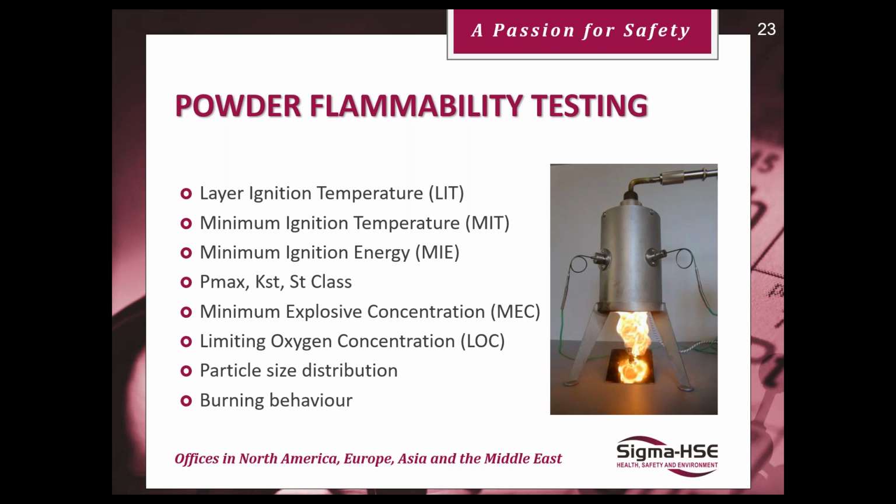And then we have the minimum ignition energy, the MIE, which is a spark ignition. Typically when we're measuring MIE values, we can do it in two ways. We can generate that spark across the dust cloud either capacitively or via an induction method. The reason they're done differently is because they mimic different types of spark.